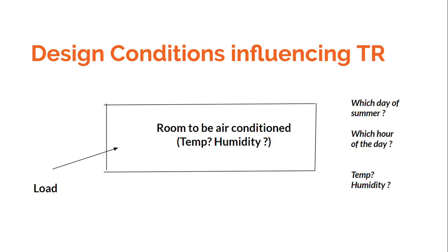So just as you have a heat balance of an engine in which there is a source of heat generation and there is a source of heat dissipation, similarly the human body can also be considered as a heat engine in which heat is produced by metabolism, and then there is a heat exchange with the surrounding by means of convection and radiation. And also there is some useful output in terms of work which the human body does. As a result of this, the human body has to be maintained at a certain temperature.